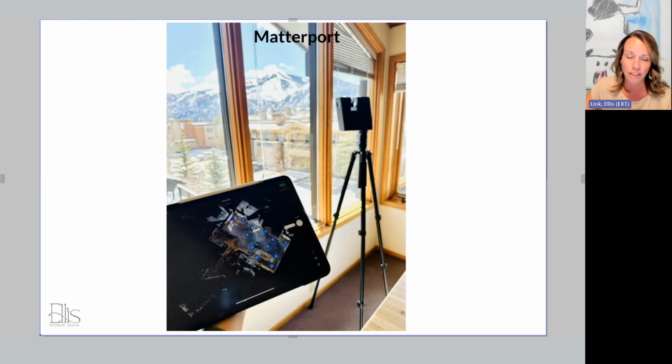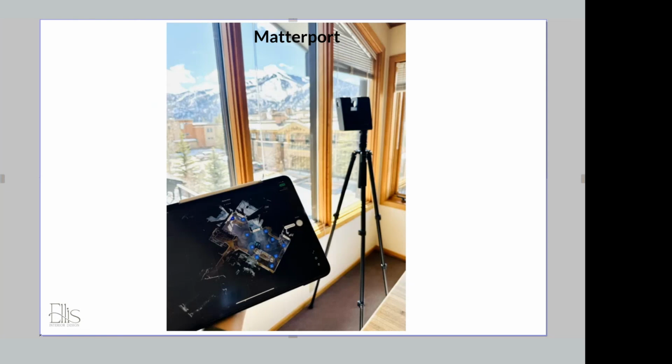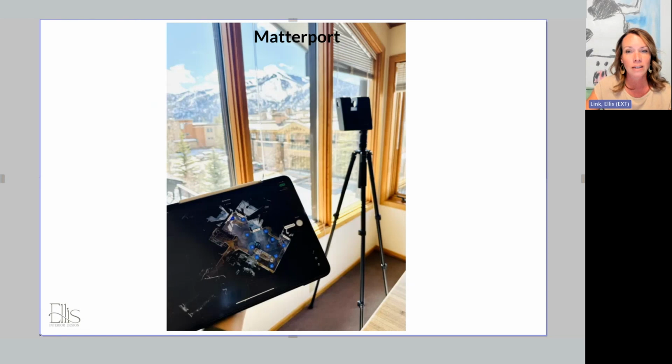One of my favorite tools to use in our process for renovations is a Matterport camera. For those of you that don't know what a Matterport camera is, it's a camera that can take a 360-degree scan of your project. From that scan, we can generate a point cloud and drop that point cloud into Archicad. That's how we start our base model.